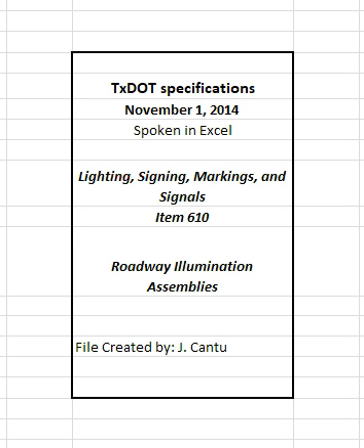When required by the engineer, notify the department in writing of selected materials from the MPL intended for use on each project. Do not provide shop drawings for complete assemblies that are fabricated in accordance with this item and the details shown on the plans. Electronically submit shop drawings in accordance with item 441, steel structures, for optional multi-sided steel pole designs, optional aluminum pole designs, and non-standard designs, required when basic wind speeds or pole base mounting heights at the installation locations are in excess of those shown on the roadway illumination pole, RIP, standard.